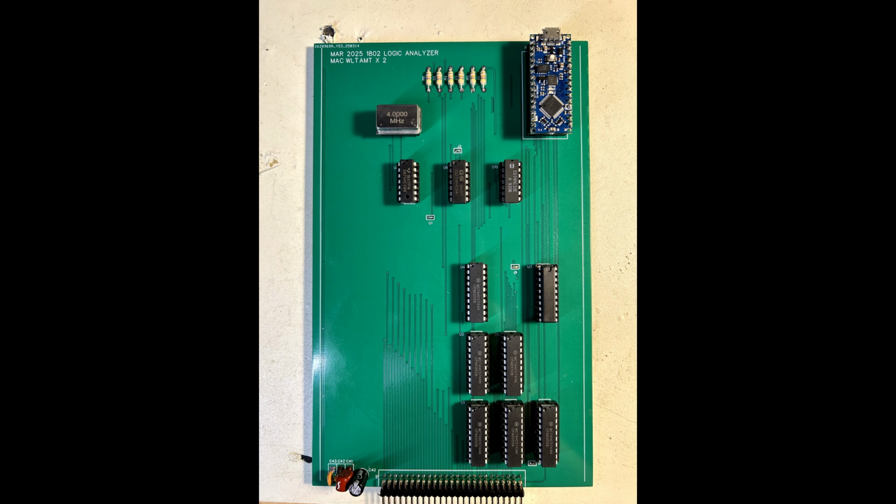The logic analyzer is very simple. A Nano Every controls it. You'll see that I've moved my system's 4 MHz clock signal from the CPU board to this board. Both boards have a socket for the oscillator, so I can always move it back to the CPU should I choose to do so later. The board circuitry allows the Nano to select between a 4 MHz clock, which is the default upon power up, or the Nano can generate a logical clock signal.